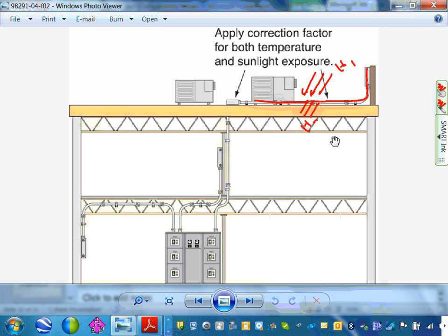That's heat number two. And can anybody tell me what heat number three is? No? The current going through the conductor. So this conduit is being cooked by three sources of heat. The heat inside the conductor, you can have nothing to do about it. I mean, they can't change it. The heat from the sun, unless you want to put an umbrella on top of it or something, you can change. And the heat reflected from the roof. So they discovered, guys, over experience, that these conductors will be cooked.